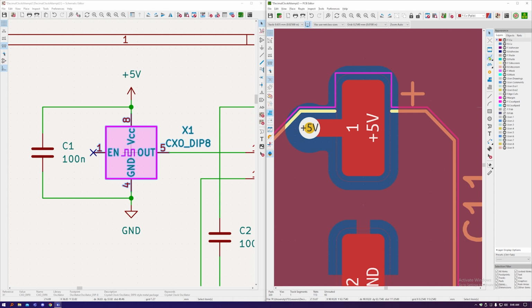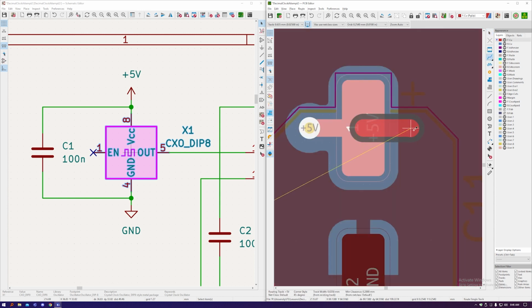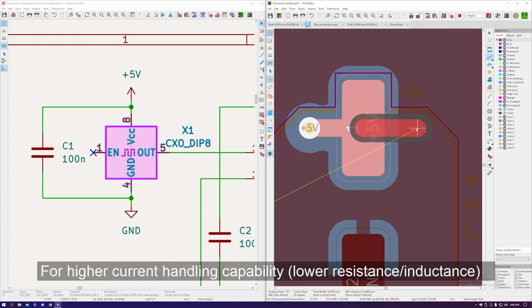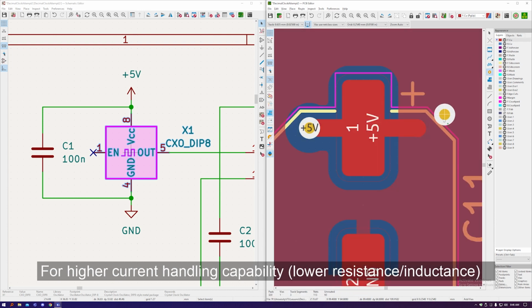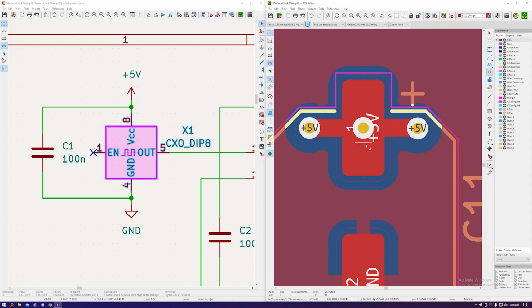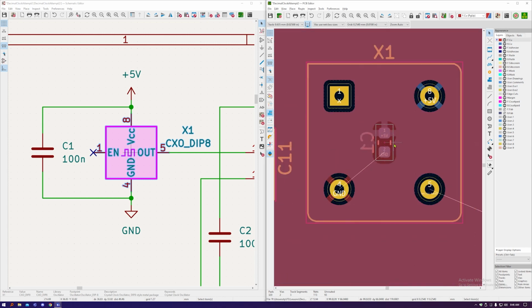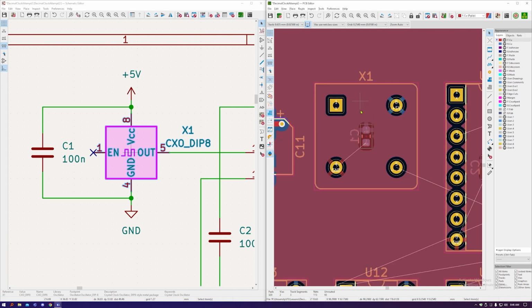And what I'm going to do, because this capacitor's fat, I think it deserves 2 connections. So I'm actually going to do the same on the other side, but that's not a convention or anything like that, so I wouldn't worry about it too much. Next is the decoupling capacitors. They're all the same, but I'll just show it for the oscillator and then repeat it for the others.